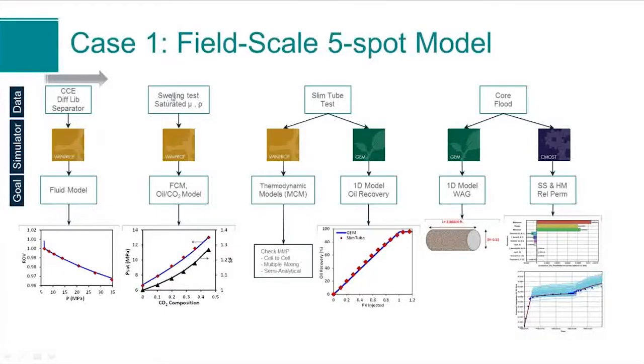Then I used the same PVT model, along with the experimental data for the carbon dioxide and oil interactions. I had swelling test results and the saturated viscosities and densities by the dissolution of the carbon dioxide into the oil. Again, I used this data in WinProp to match the first contact miscibility and also the oil and carbon dioxide interactions.